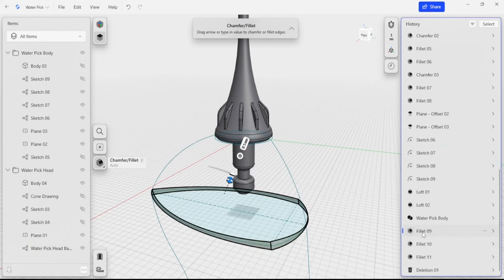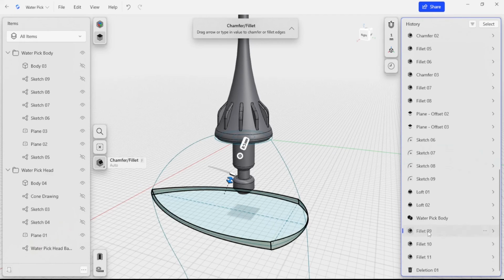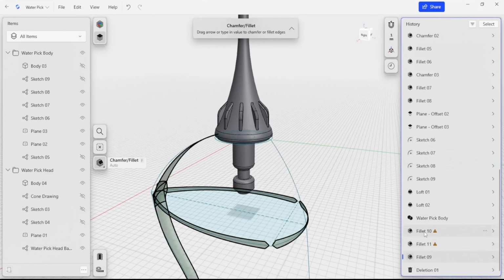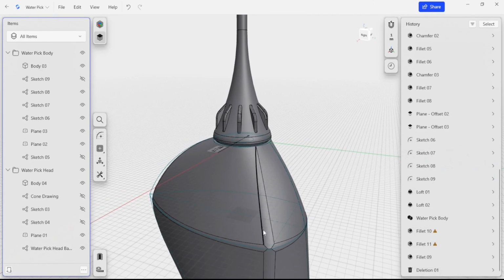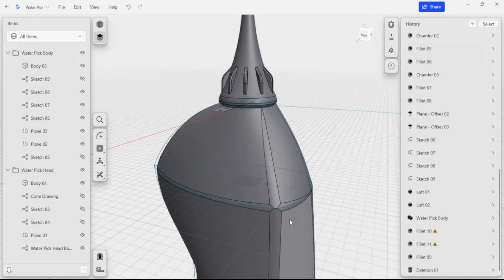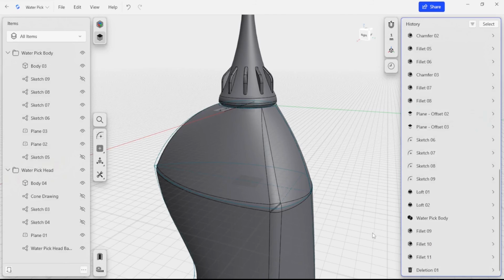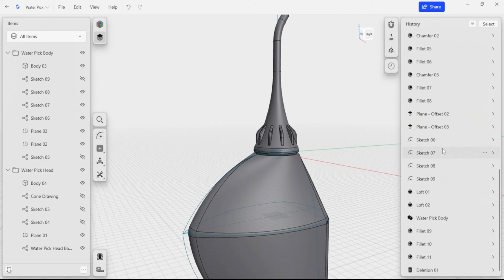So for example, if I start to move these fillets. This fillet here was done purposefully before these other two fillets in order to ensure that we were going to get a clean design. If I move this around and I change the order, you might see that things break down. So these two fillets no longer render properly and they become problematic. So I can turn that body back on. You can see that we're not getting very good effects. So one of the things to think about is really the order of operations and how we can best present those things so that we can edit them and move them around without breaking down.